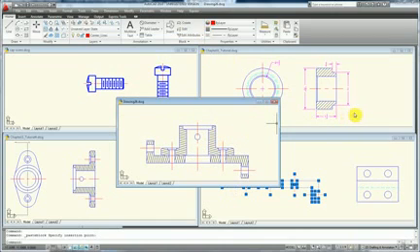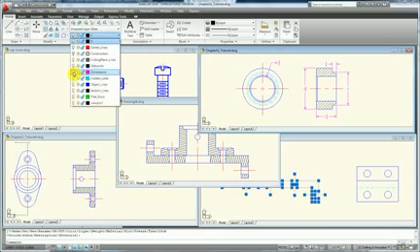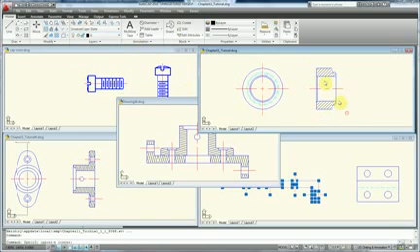To do that, we're going to go to the collar section, and first thing we're going to do is take away the dimensions. Once we've done that, we're going to do the same thing we did with the bearing. So we're going to select it, right click, choose copy with base point, choose a base point that again is referenced about the center line and about some reference base geometry that you're going to use to relate it to another piece of geometry.